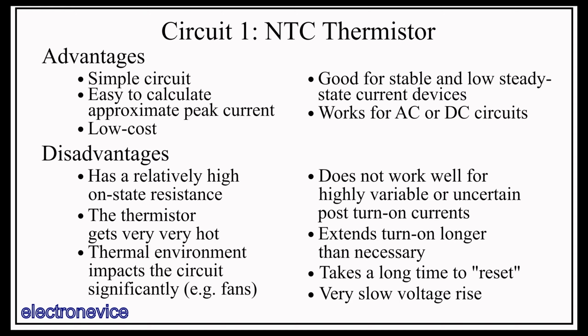Finally, the voltage rise is very slow and takes many seconds before the thermistor series resistance has minimized and the load voltage has stabilized. This can be an issue for lower voltage systems, as often you'll have downstream devices that have their own soft-start circuits that are triggered by the input voltage rising. They might start their soft starts, start drawing some smaller inrush currents of their own, droop the voltage rail, trigger their internal undervoltage lockout circuitry, wait, then start over.